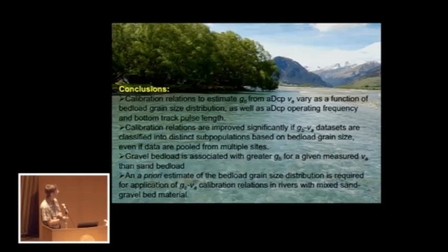And I think you need an a priori estimate of which grain size distribution is in transport in order to choose which calibration relation to use. But I'll emphasize, I think the calibration relations may transfer from site to site. Okay, thank you.